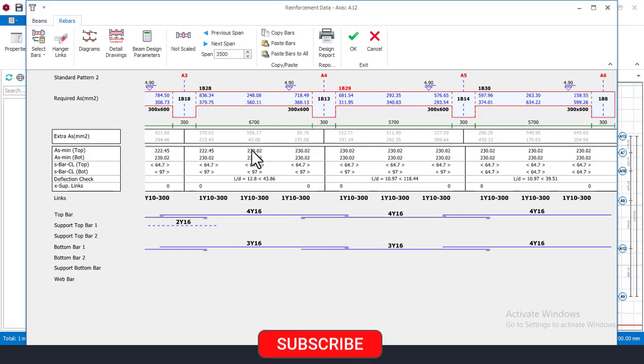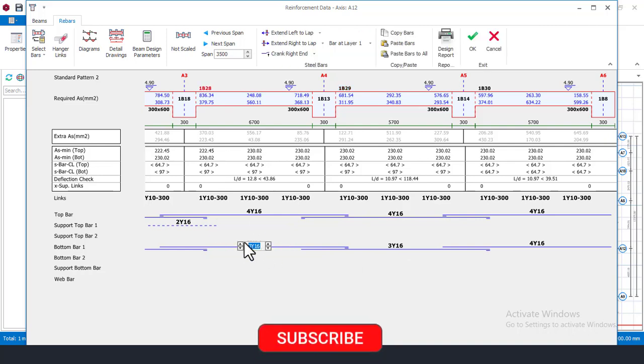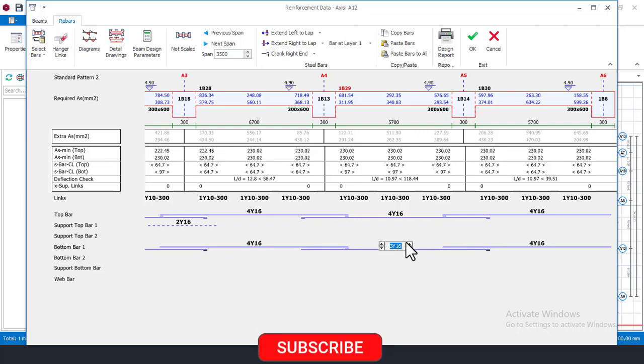3 numbers. But I think this space is having lesser number. I can choose to work it through now to have 4 here, just to increase the area of steel here at this place. That's fine. And also, with this now, I'll have to make it 4 to have a smooth flow of reinforcement placement during the construction.